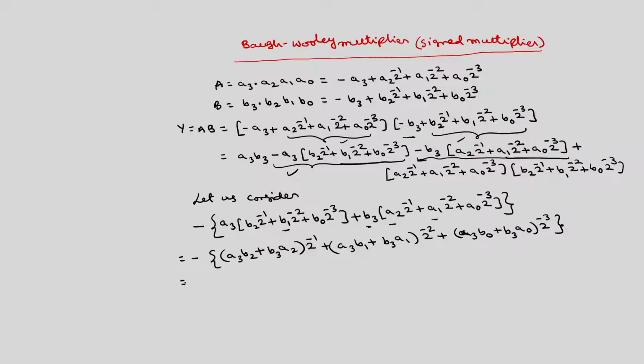Now, here I am going to write this as, if a is a Boolean variable, in general a is a Boolean variable, I can write a as 1 minus a bar always, because if a is 0, a bar is 1. So, this 1 minus 1 becomes 0. If a is 1, a bar is 0, this is 1 minus 0. Okay. So, always you can write a as 1 minus a bar. Okay. This is what we are going to write here.